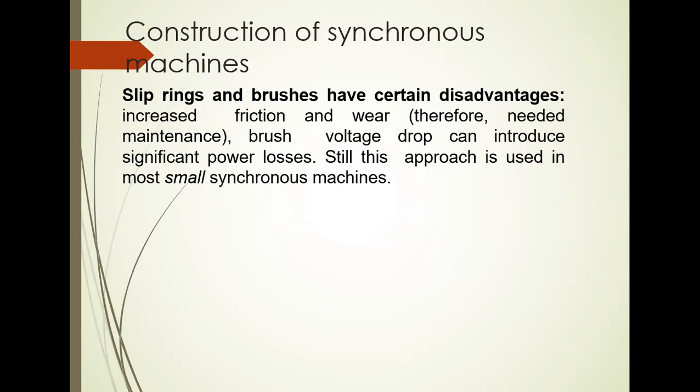So what are the limitations of slip rings and brushes? Here it induces some friction and wear. Brush voltage drop can introduce some significant power losses. But the slip ring and brush assembly is adopted for small synchronous machines. Already I told.